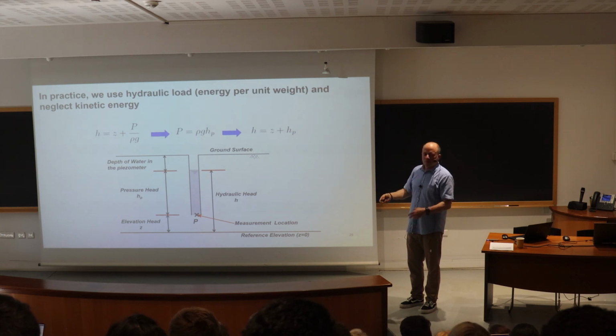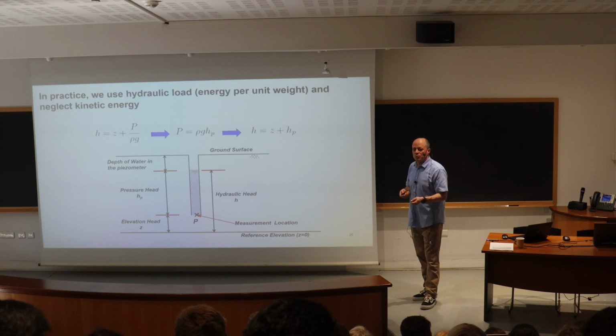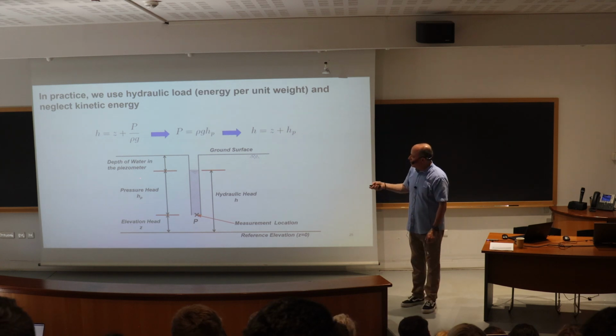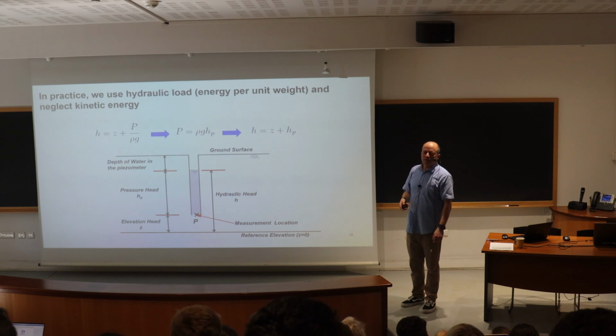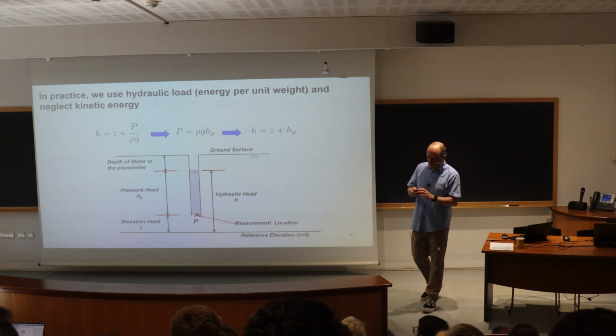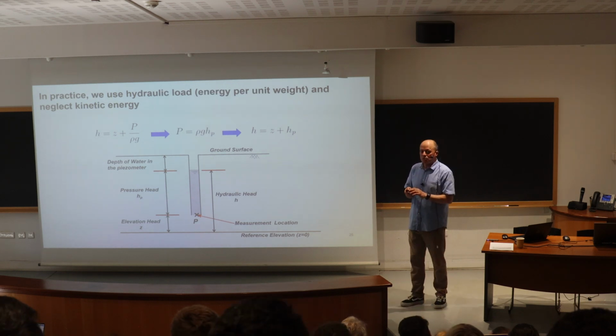And when we go out in the field, what we measure is the depth to water in the piezometer if we have a manual measurement. Otherwise, with a pressure transducer, we would measure the pressure. And we use these measurements to convert back to the hydraulic head. And that is an indication of the energy of water.